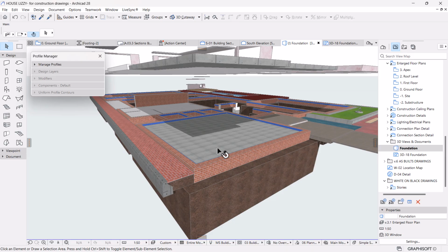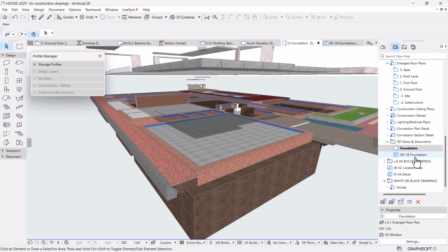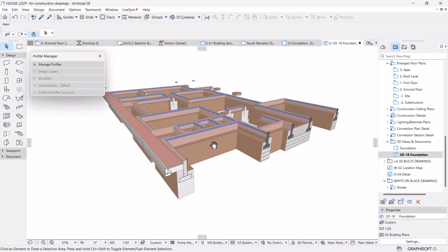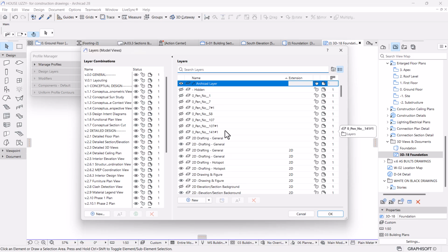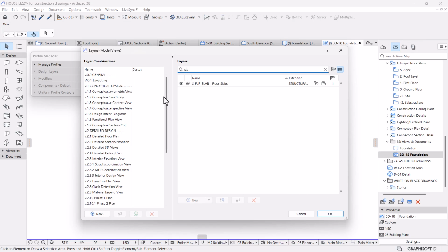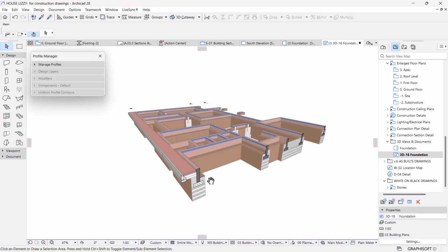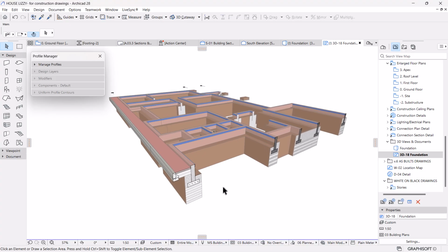So when it comes to, oh, I see. I wanted to transfer the floor slab to this one, but if you say right click and say slab, it doesn't show because the cut wasn't going across. It's a pity that we didn't have it here, but it's something that we can really see.